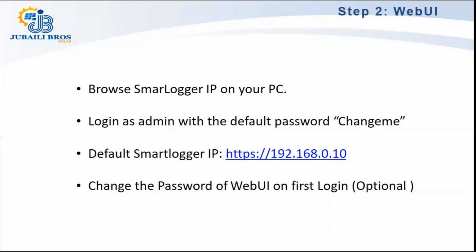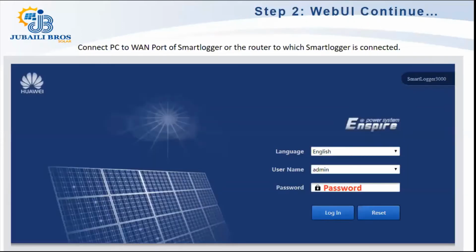Then you will be logged in as an admin, or as an advanced user if you are using the old Smartlogger. Once you log in, you will be asked to change the WebUI password on first login, which is optional. If you want, you can change it. Otherwise, you can keep it unchanged. So this is the window that will appear after you put the IP address of the Smartlogger in the browser.